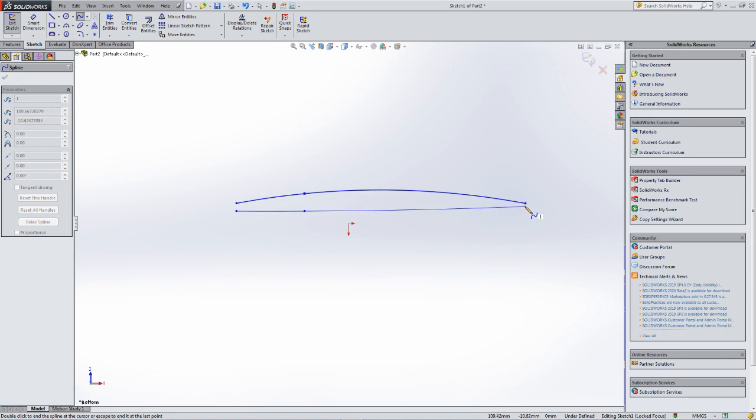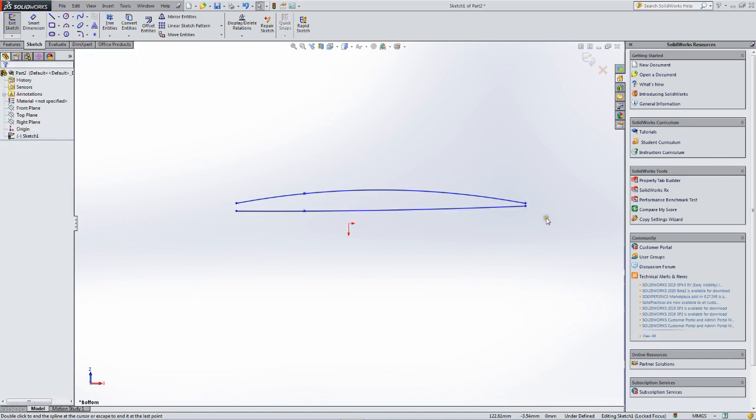Now I'm keeping the trailing edge blunt. The program tries to snap to a sharp trailing edge, you can see there, but I'm pulling away and not allowing that to happen, because when I go to 3D print this thing, if I have a sharp trailing edge, the resolution of the printer will cause me to lose some of the planform area back there.